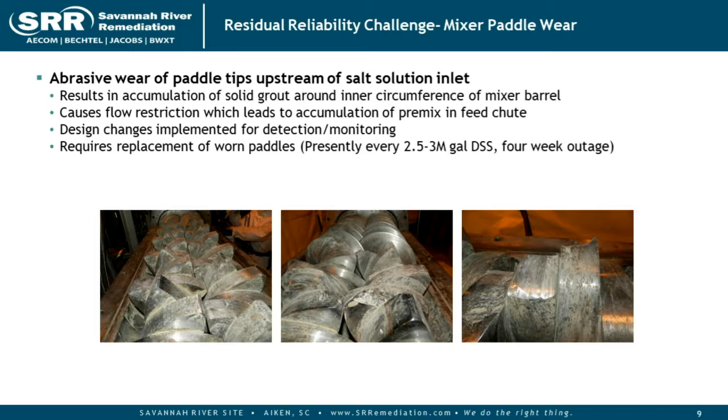And it will start out being a thin crust, but as it opens up to this size, that's about 3/4 of an inch, you effectively will begin to create a rind within the mixer that is reducing the overall cross-sectional area that's available for flow. And when that gets significant enough, you actually won't be able to de-inventory all of the dry material that you're sending to the mixer. And that dry material will then begin to accumulate in the chute upstream.